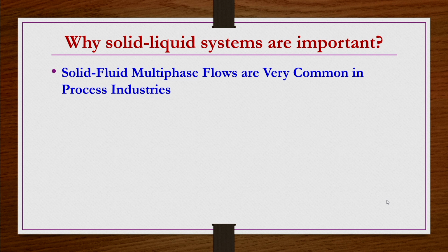So, what are the situations where we generally have these solid fluid systems involved? Something like flow through packed and fluidized beds. Packed beds are sometimes used for heat recovery systems or heat storage systems. Fluidized beds are in general used for coal combustion, etc., or some catalytic reactions. For those purposes we generally use them, where there is a relative motion between solid and fluid systems.